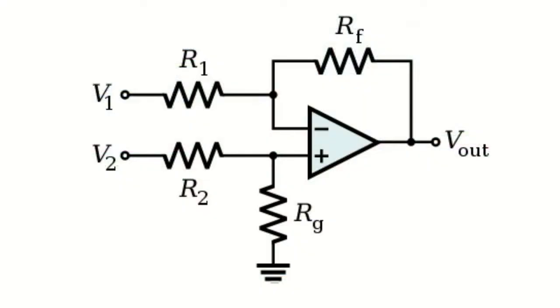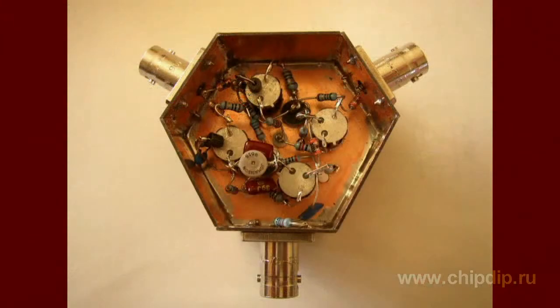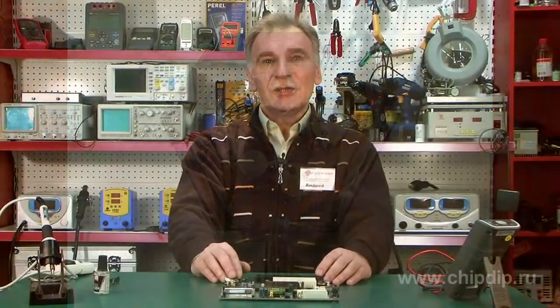Operational amplifiers are used due to the following properties: very high input resistance, very high gain factor, 10,000 and higher, and very low output impedance. There are more than a dozen of typical layouts of inclusion of operational amplifiers, each of which has its own characteristics, for example, a comparator, an inverting or a non-inverting amplifier, or a frequency filter.